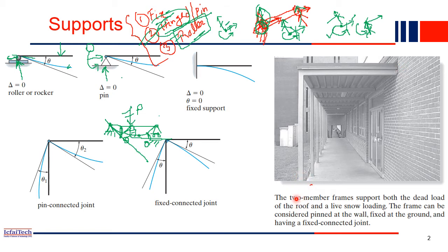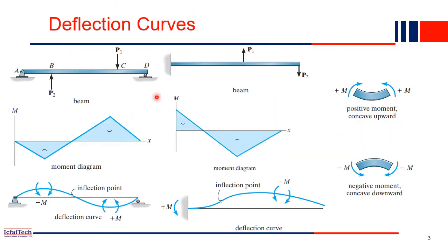This is fixed, grounded here, and this joint is basically a welded connection, right? So this is also a fixed connection. This joint is also welded, meaning a fixed connection is there. That's how we make our original structure into analytical models. These are the analytical models, and we do our structural analysis. So in this lecture, we'll see how exactly you can draw a deflection curve.